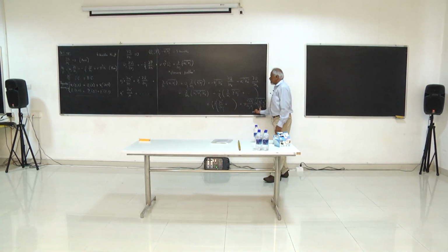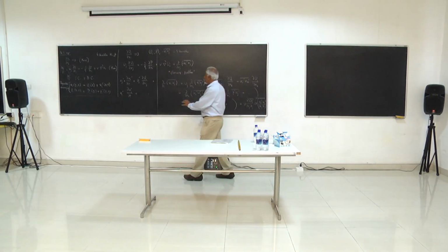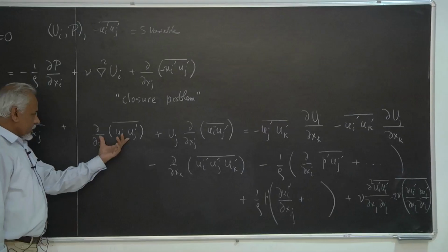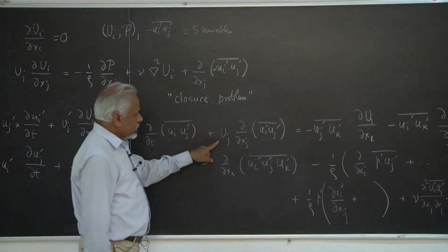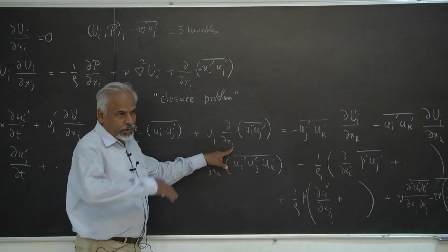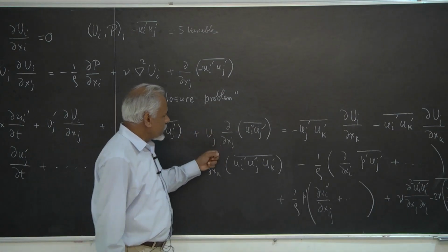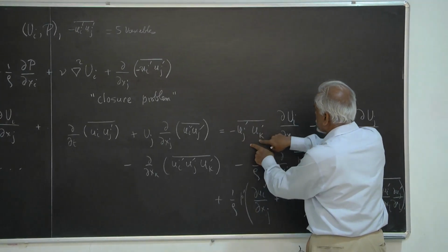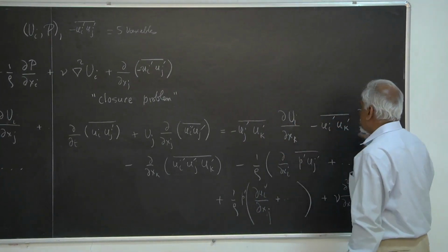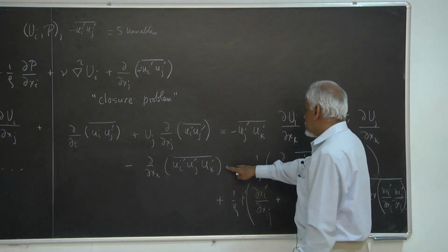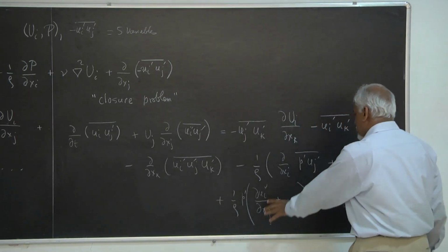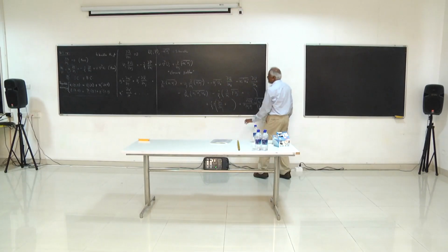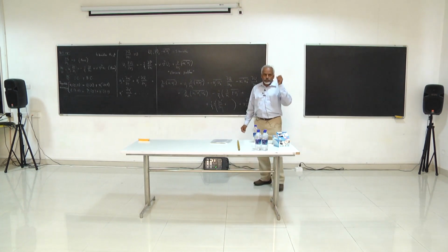And then I have the viscous term. So if I am thinking of this as a conserved quantity and I'm writing an equation for it, this is the rate of change in time, and this is the advection along streamlines, mean streamlines. And then I have quantities that involve the fluctuations and the mean gradients in the flow. And I have these third order purely turbulent quantities involving pressure, velocity gradients, and pure viscous terms. So I have all this stuff.